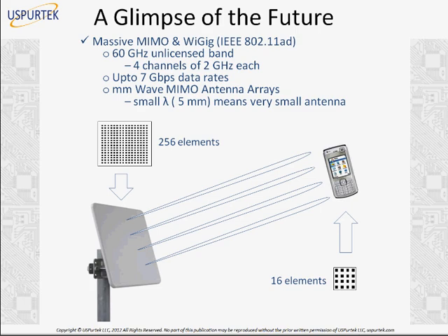Now, of course, here the frequency is 60 gigahertz. Currently, there are some applications where we use this high frequency for wireless backhaul. Wireless backhaul means when you connect a base station antenna to the core network, you use high frequency because you need more bandwidth. You have to carry so much data from different users connected on the wireless network that you need a high frequency to carry all that bandwidth. 60 gigahertz, and there is another higher band available, 80 gigahertz. So 60 and 80 gigahertz are the bands available for high bandwidth wireless communication. It's mostly point-to-point communication in that case.